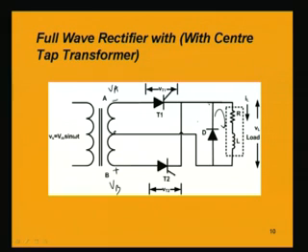But when VA enters into the negative half cycle, the diode conducts, the thyristor T1 is now turned off, since anode is negative, and the load current is due to the diode current.